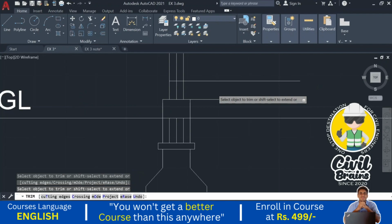Clear? So this is our isolated footing of depth 0.6 meter, which is reduced to 0.3 meter. Okay, so why are we going to give this slope? Because to save the concrete. If it is unnecessary, we are not going to do the concreting work for any structural components. So from the economical cost point of view also we need to do this. Okay, so here you can see we have provided this.